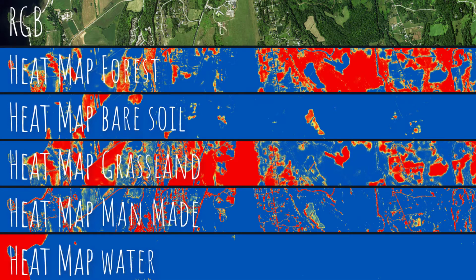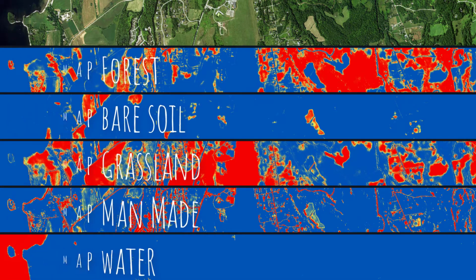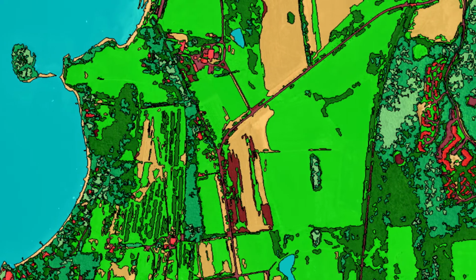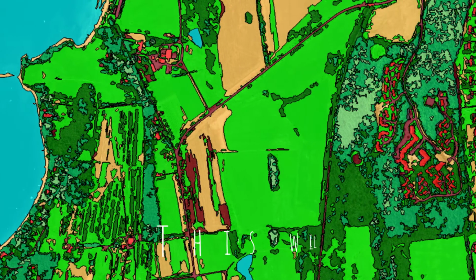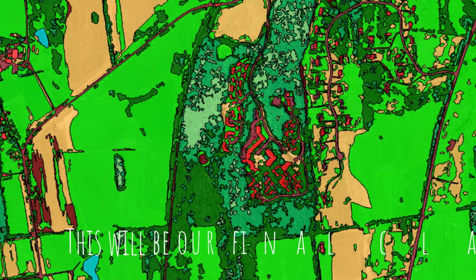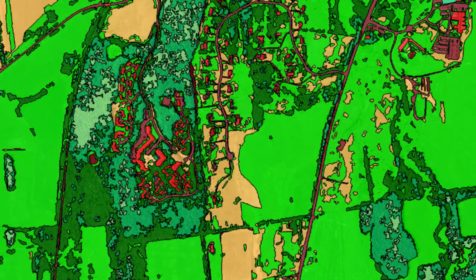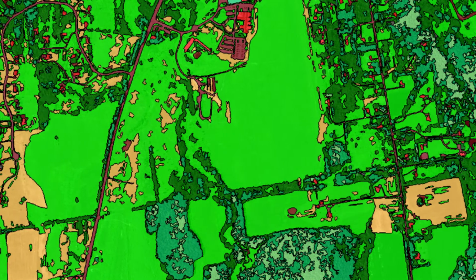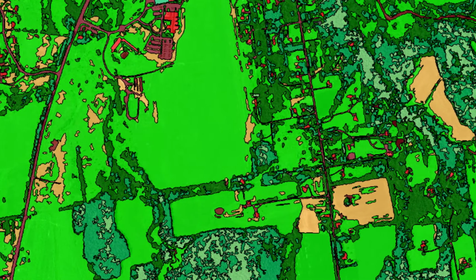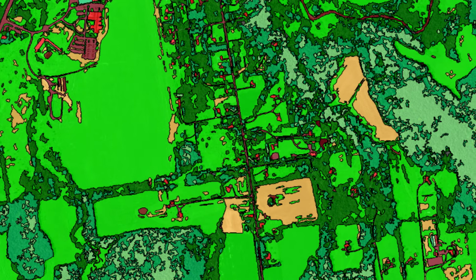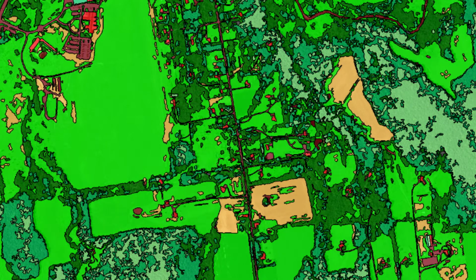We're also gonna then apply object-based image analysis methodologies to create a nice land cover classification. And we're gonna do validation as well on the second subset. The accuracy assessment gonna be an accuracy assessment of the final classification compared to validation data that I have. You also can run an accuracy assessment of the model itself, which makes sense, but in this case I'm going to try to keep it as simple as possible, showing you really the most important algorithms that you will need to implement a meaningful deep learning workflow in eCognition for land cover classification.